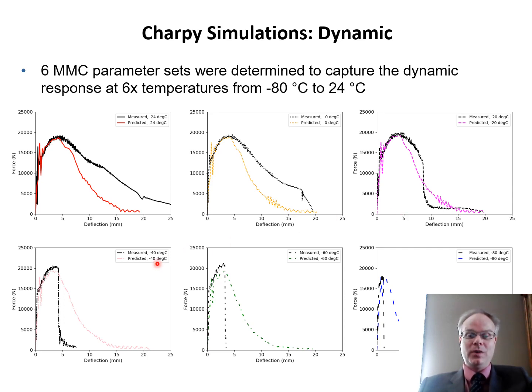One aspect that we are not capturing, particularly when there's brittle cleavage fracture, is the sudden load drop in the material. No matter how we change the coefficients, we're always getting an increasing energy with increasing displacement with the ductile damage model.